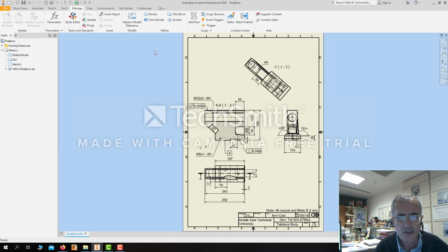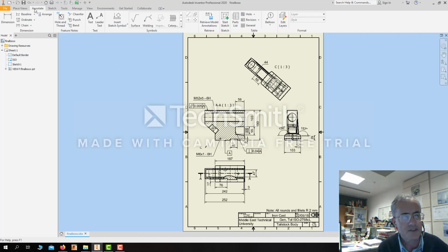of the standard, in Turkey at least, most of the companies still use the version of 1978, accordingly showing the surface texture symbols. So regarding that it is so, that's why I started from here, selected the old version, and then the Annotation tab, and in the Symbols panel find the Surface Texture option with a click, start the process.